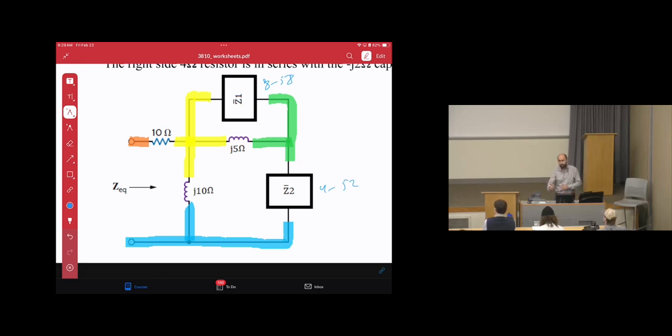So again, as we know in finding equivalent resistance, now it's finding equivalent impedance. After you do every step, we will redraw the circuits for doing more simplification. So we have Z1 and j5. Again, start from the furthest point away from your observation. So Z1 and j5 are in parallel, between yellow and green. Then we can do their parallel.